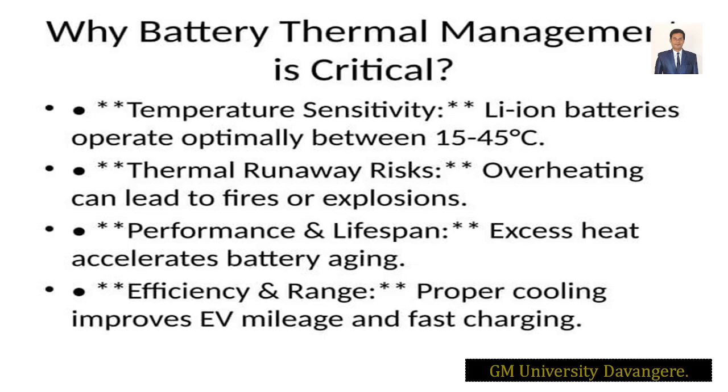The temperature sensitivity, which is to be around 15 to 45 degrees, is the optimal temperature. Please make a note of it. The battery thermal management system is very critical. You have to think about the lithium-ion batteries, which operate in the range of 15 to 45 degrees centigrade, right? And the next factor is the thermal runaway risk.